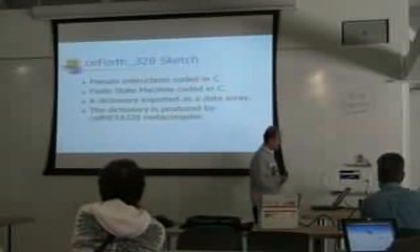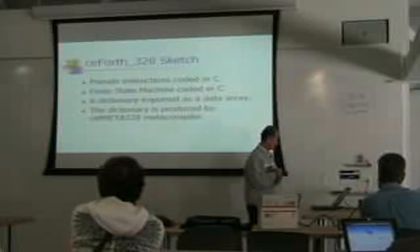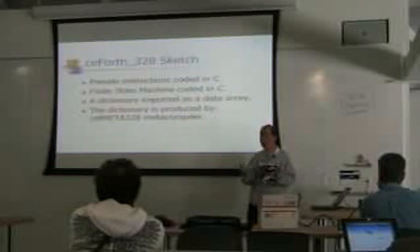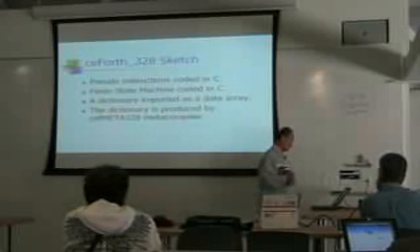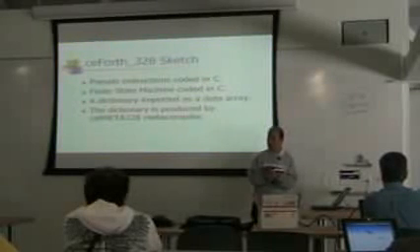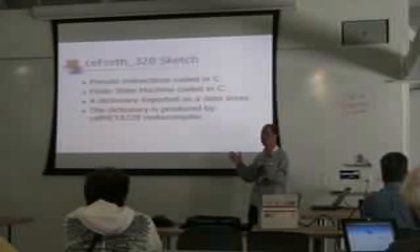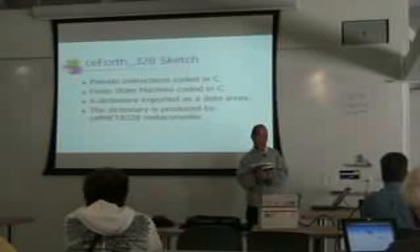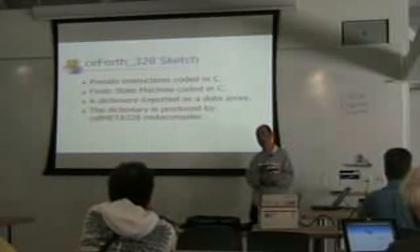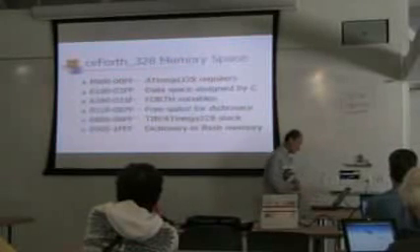The final system I built is called eForth 328, and it is written as a sketch. The sketch is an Arduino program that you can compile and run. Pseudo instructions are coded in C. The finite state machine is also coded in C. The dictionary is in a data structure, a data array, and this data array is produced by a metacompiler and copied into the sketch. With that, we have a complete system.